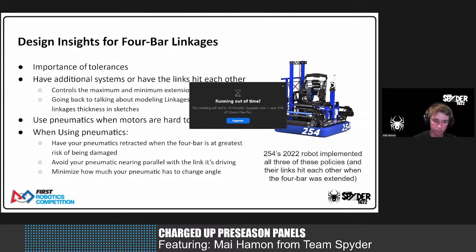This caused a lot of problems for my linkage because it had a much harder time retracting, meaning the pneumatics in the mounting bracket for the intake took quite a beating after being exposed for so long. This problem was so vast and so rooted in the design that you couldn't fix it with a mechanical solution. But had I gone to the design process much earlier and simply moved the pneumatics, it would have worked the first time.